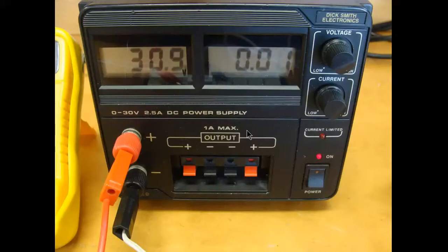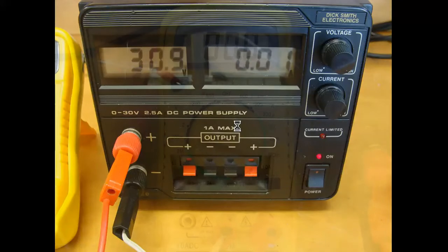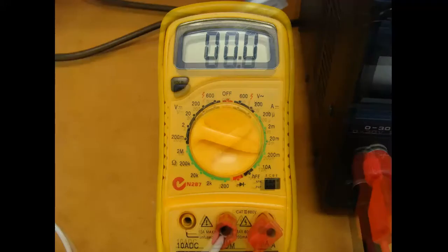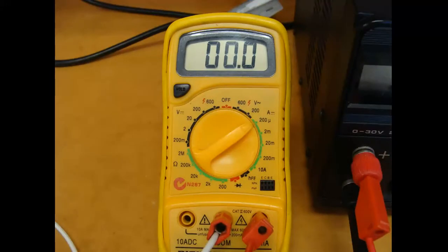We're going to set the power supply as high as we can. This has gone up to 30.9 and measure the current flowing through the circuit. Now on the 200 milliamp scale it is 0, no current, which is what we would expect. But we can look at a different scale. We can go down to microamps, but still we're getting 0 current. Now some of you may get some current there, that will be okay. Very low microamps can be expected in reverse bias.